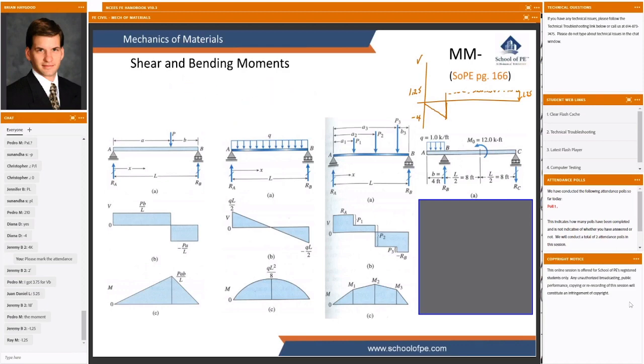It's going to start with a slope of 0, because I know my shear diagram starts with a value of 0. So we'll start with a slope of 0, and our slope is going to get increasingly negative over the first 4 feet. At the 4-foot mark, I think we're going to have a local minimum, and what will the local minimum value be on the moment diagram at the 4-foot mark? I'm going to start with a slope of 0 and end up with a steeply negative slope, so my moment diagram is a parabolic, concave downward thing.